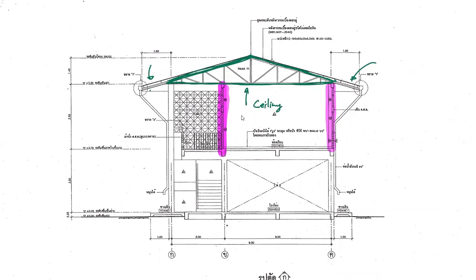So that means when you study the configuration, you go back here and you know that not only will your truss have to support the live load of the roof and the dead load of the tiles, the roof type that you use, you probably have to consider the ceiling as well. What kind of ceiling you want to use, and do you want to have insulation maybe? Something like that.